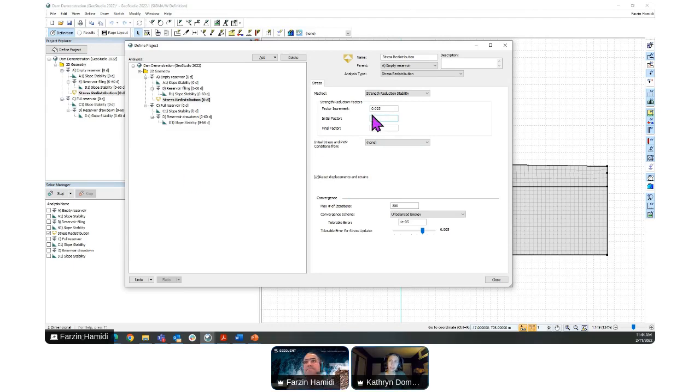Yeah, so there are some cases where using Sigma W is suggested when we're looking at stability. For example, if you're looking at soil structure interactions, it's important to use Sigma W to assess the stresses in the ground, because the limit equilibrium method, though it's lovely and straightforward, and we use it a lot in GeoStudio, does have some limitations when looking at reinforcements.